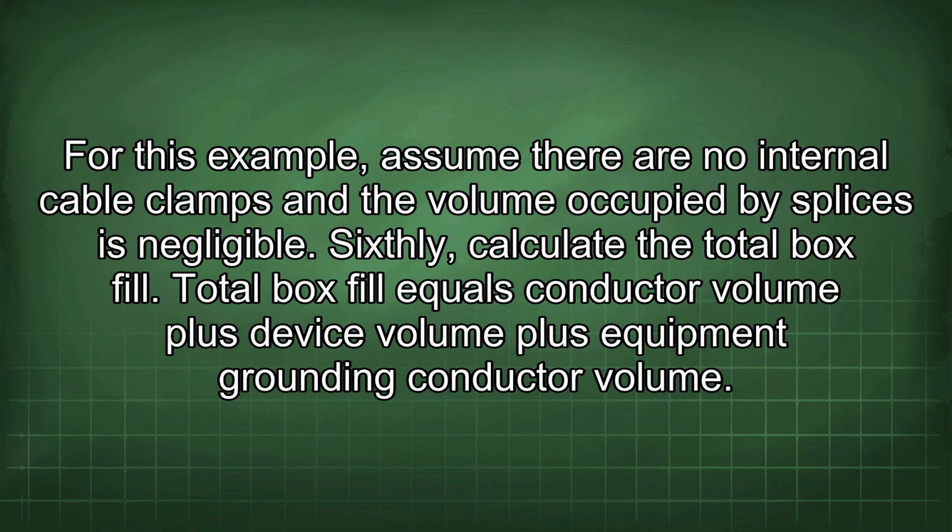Fifthly, calculate the volume of any splices or cable clamps. For this example, assume there are no internal cable clamps and the volume occupied by splices is negligible. Sixthly, calculate the total box fill.